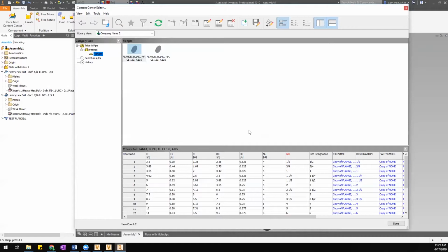Yeah, so essentially, like what Cameron's saying is there was a change made to the actual model, right? So some features got removed. All of the components that we had dropped prior to this change will have that raised face on them on Cameron's computer, right? They put the part files in some folder location. So what you need to do is you need to get rid of those and replace them with parts made by this model, or else you'll have raised faces. Yeah, you'll just have the old version of that file.